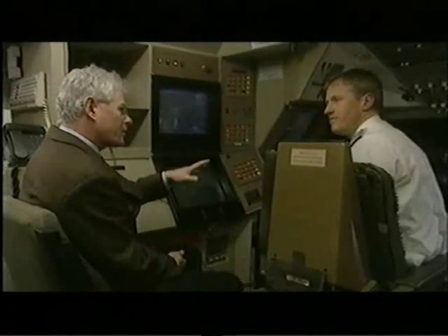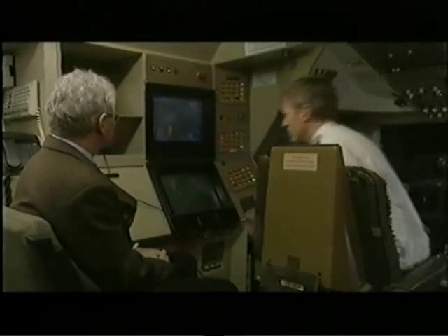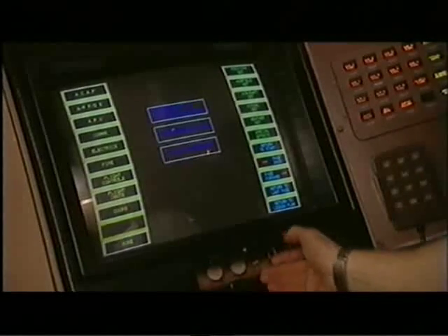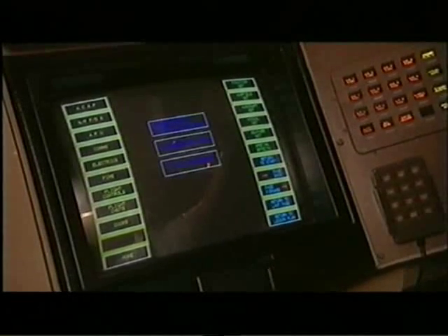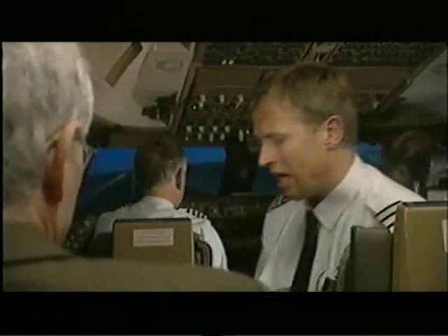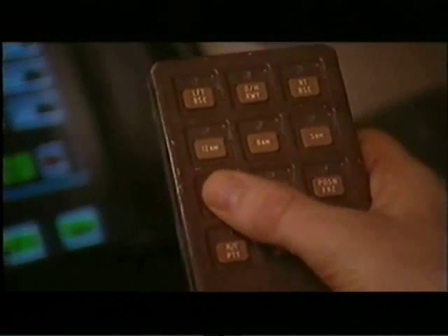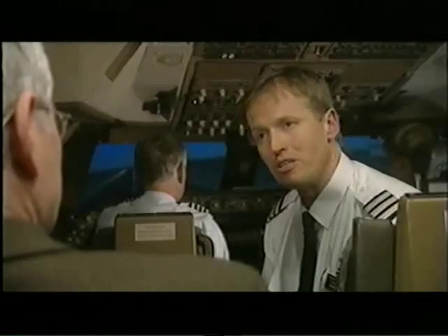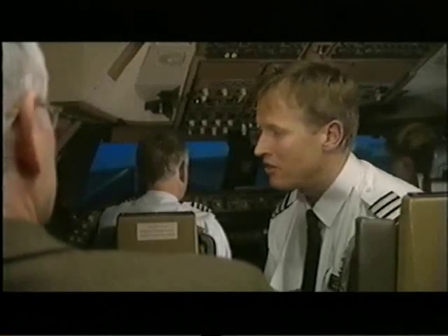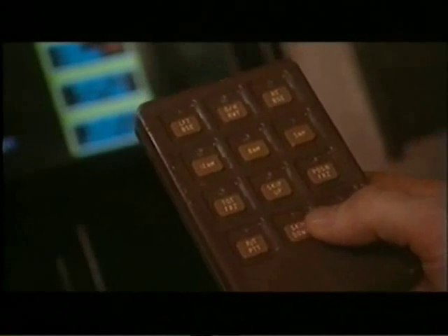So when you first come into the cockpit, exactly how would you find this? The same as you see before you here, both screens will be turned down, and I need to adjust the brightness levels accordingly. And the visual page may have the visual indicating blank. And the light on the IPCU will be flashing for the total freeze, and that'll need to be deselected as I've done here, and that'll allow the crew then to commence their pre-flight check. And then if we're commencing a lesson plan, I select the detail on the lower screen, and activate it using the instructor's portable control unit.